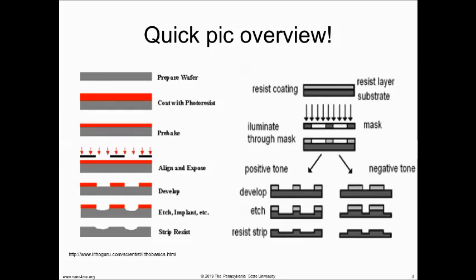So that's how you would put that resist on. You spin it on and smooth it out. Does that make sense? We don't have a smoother in this case by that analogy, but we just put on the liquid, then we hit a spinner, and it uniformly coats across the wafer. Does that make sense? At that point, we're at the step that says pre-bake.